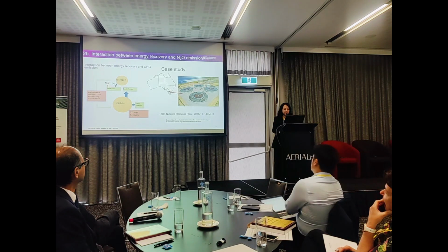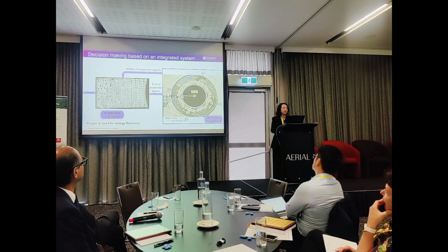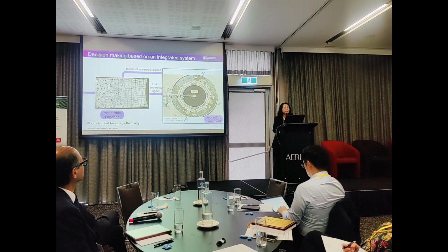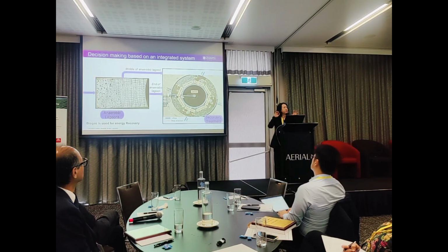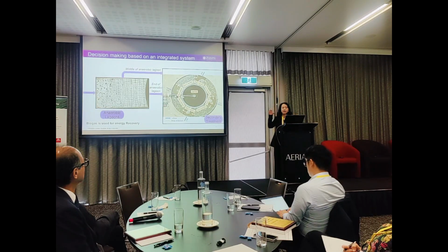This is a case study that we did in Victoria, in Melbourne, with a 4-step feed plant. The wastewater first comes from an anaerobic lagoon that is used to generate biogas, and the biogas is captured. After that, it is sent to a 4-step feed treatment process. I probably will not go through how it works, but basically the flow is split into different steps. Normally the first one has 40%, and later ones reduce, until the fourth treats only 10% of the wastewater. That's called step feed. We try to remove nitrogen by steps.